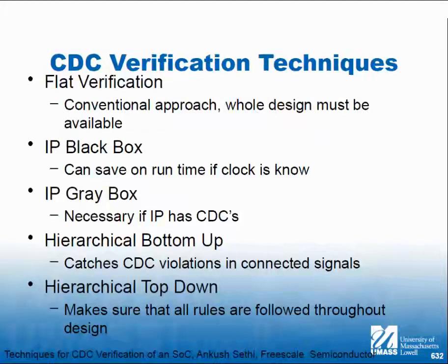Now, I wouldn't have every verification engineer looking at one little part of the design. If you're going to really expose this and really get into the white box method of verification, you have one person who specializes in that. Also, I think of the tools like Spyglass, Lint, the static verification tools, as being white box testing, because they're looking at the code and every detail of the code.